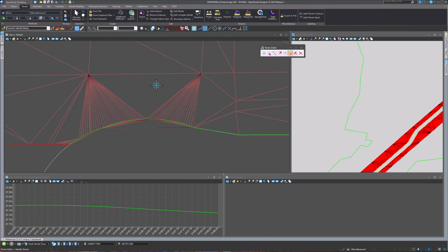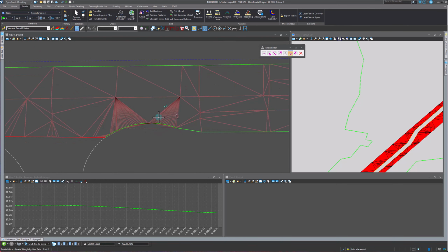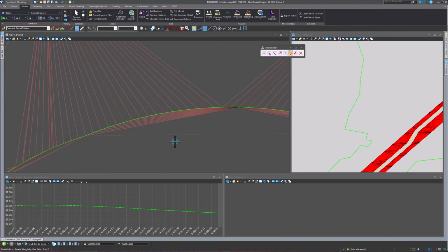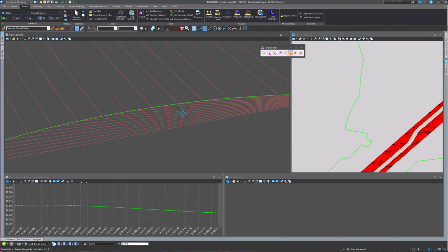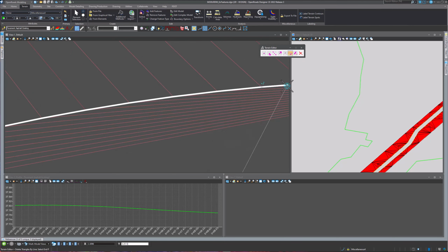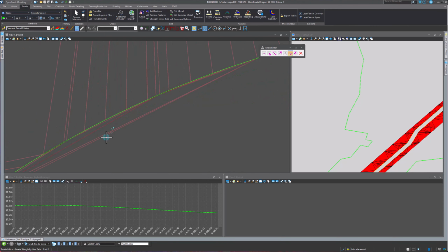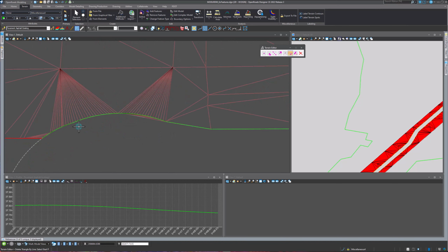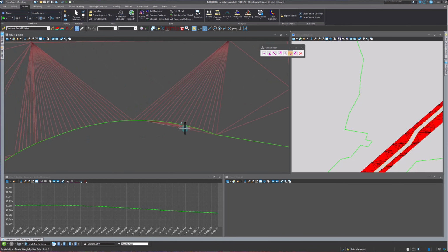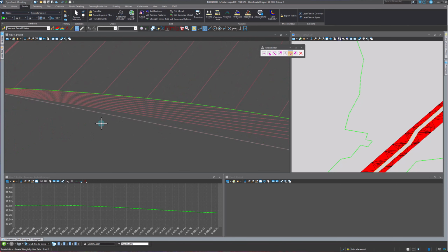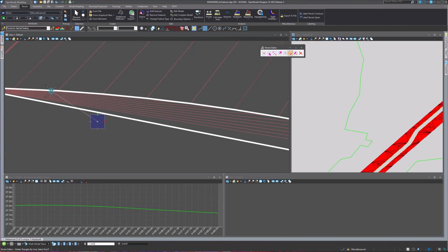Previously, you had to drop the terrain model and then edit it and then reapply or turn it back on or something like that. But now you can edit a featureized terrain model. So really, we just want to select the terrain model you want to edit. And I'm on here on this delete triangles by line. And if you start just drawing a line, you can see the triangles that it's going to delete. So I'm just trying to delete as many of these triangles in here as I can. So we're just kind of whittling this away. And if you've got a couple left over like that, it's not the end of the world. It's just existing. But let's just see if we can get rid of as many of these as we can.